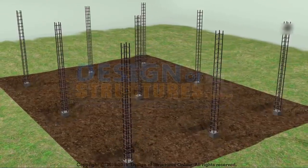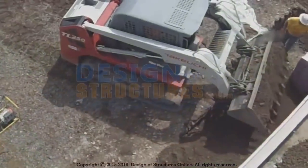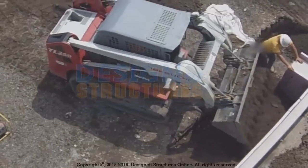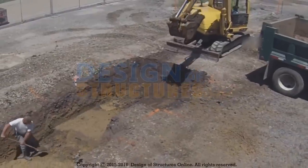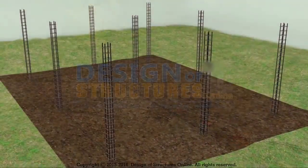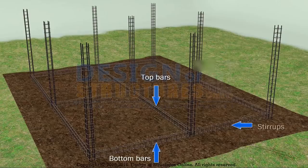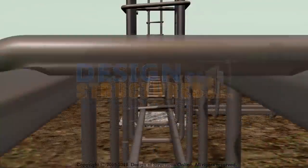Backfilling. Once the foundation is completed, backfill the remaining excavated area around the foundation with soil. Backfill provides stability to the building. Plinth beam. Beam reinforcement shall be as per drawings. Top bars, bottom bars and stirrups to be placed with proper development length.